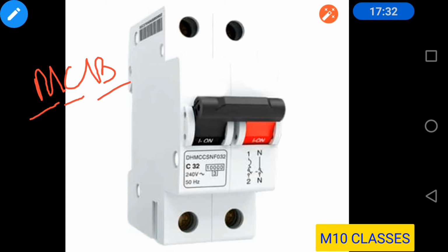In case of a fuse, if it melts, you have to replace it, but here there is a simple replacement. In the case of an MCB, if the current becomes more than the rated value, it trips off. When it trips, it breaks the circuit and the current doesn't flow to the circuit and doesn't affect the appliances. And you don't need to replace it, you simply turn it on. If it trips off, just turn it on and you'll get the electric supply. So it is an efficient replacement of the fuse.